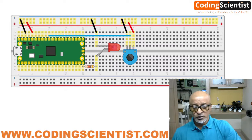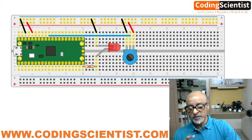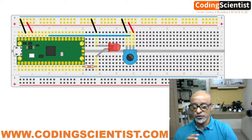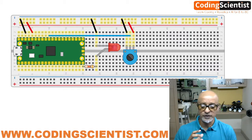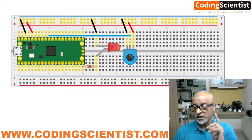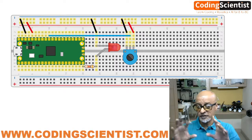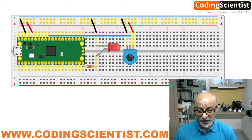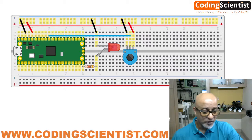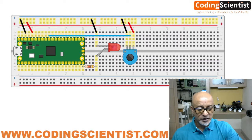Now, as you turn the potentiometer to see your maximum and minimum values, the value should be between 0 and 65025. Now you can understand, in the previous lesson while I was writing the code, you might have been wondering what that 65025 is. Well, that is the value. You are going to see this right away. All right, let's take a look at it, guys.